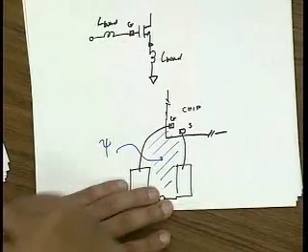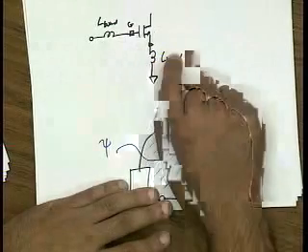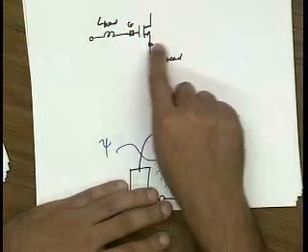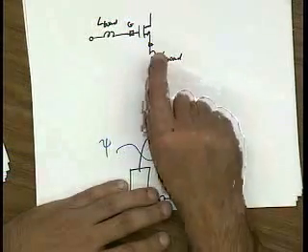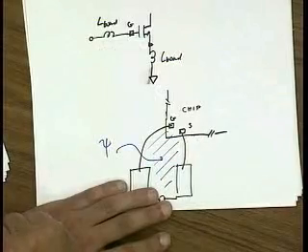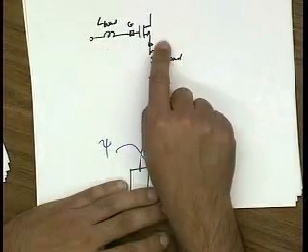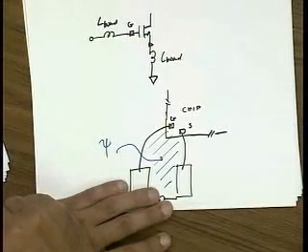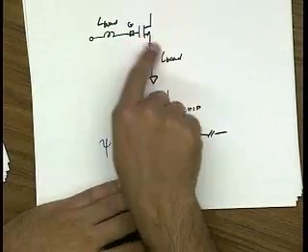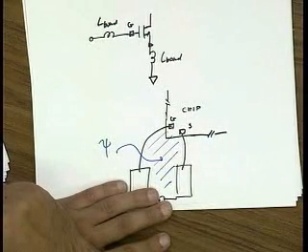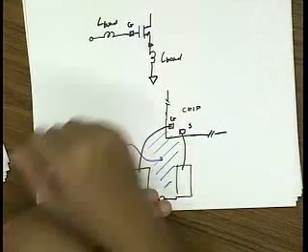And the second thing is we see this general structure, which we saw before, if you remember. Whenever you degenerate a transistor inductively, it produces a real part of the input impedance. So series inductive degeneration generates a real part of the input impedance. And that real part we can use to synthesize, let's say, 50 ohms to get an impedance match. Okay? So we'll look at that next lecture.